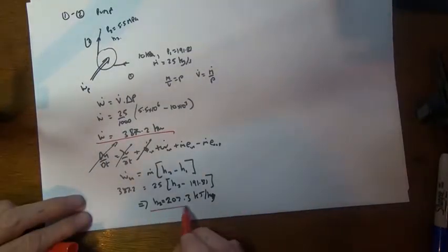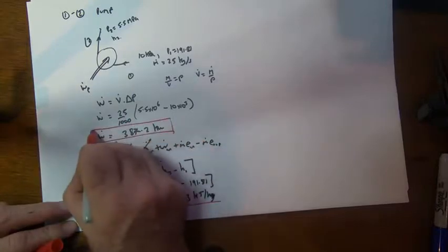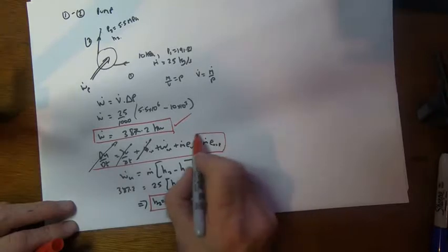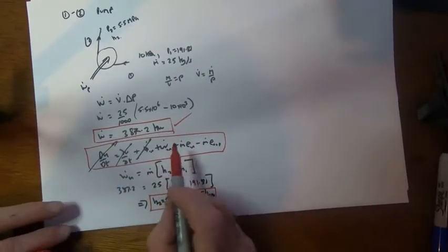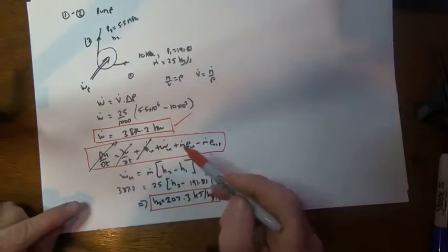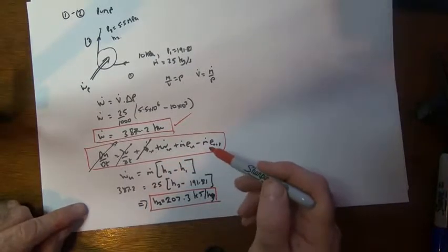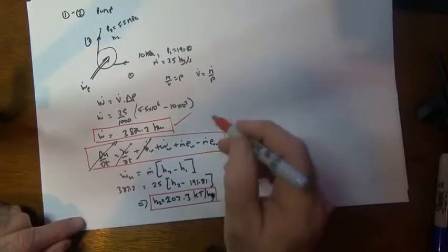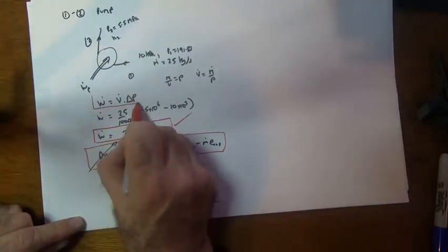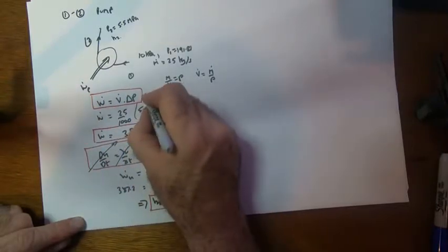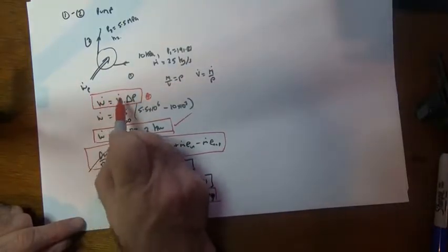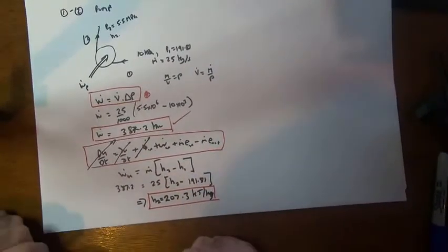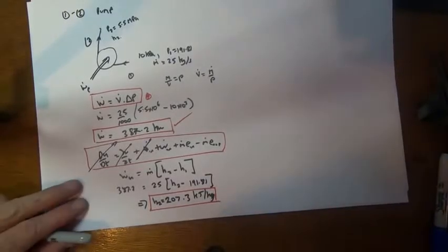So it's kind of the cart following the donkey there, because I actually found the work and then I used the work and my first law energy accounting. I could have started with this energy accounting equation and I would have realized that I don't know the work and I don't know h2. I would have had two unknowns, so there would have been a problem with one equation and two unknowns. But remember this equation for pumps works only for pumps with liquids. That allowed me to solve for the work, and therefore I could then solve for the unknown enthalpy h2. Okay, so that's the pump done.